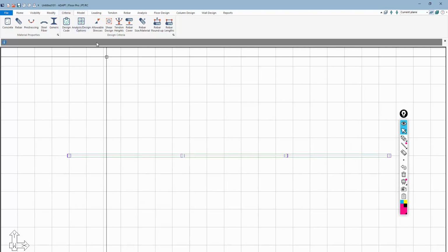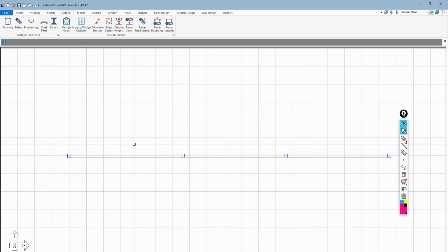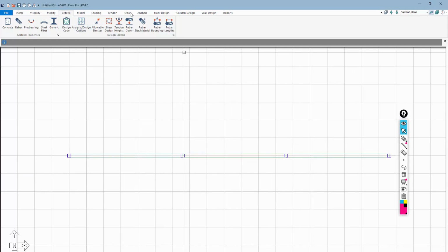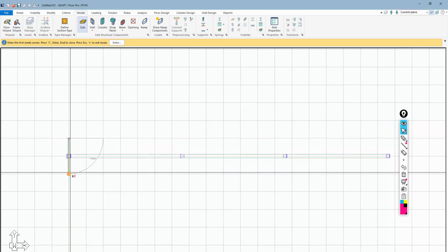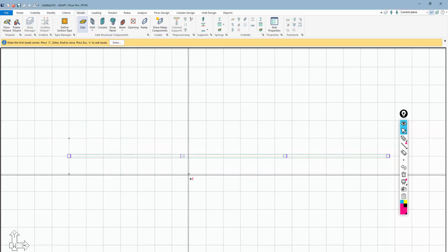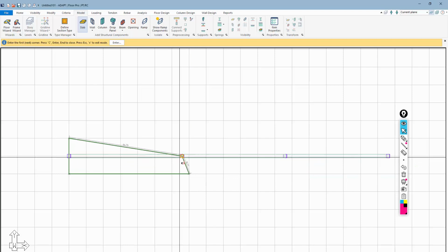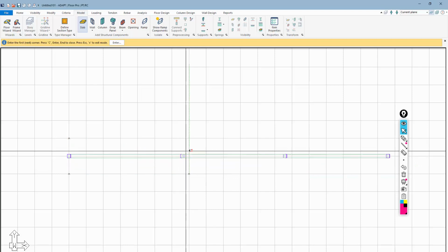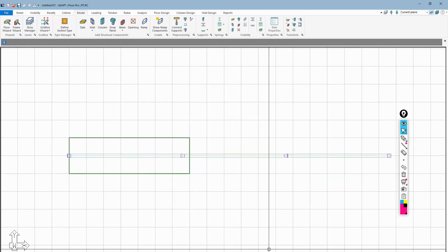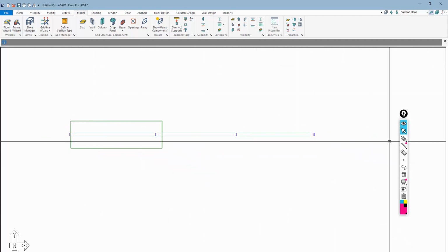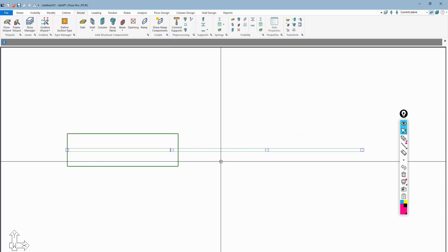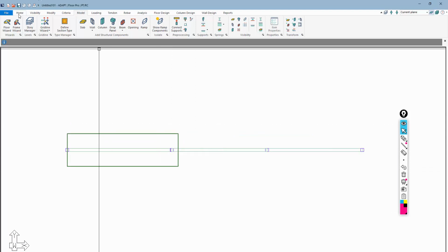Okay, so now because this is stepped, I actually need to create 3 unique slab regions. We'll go to Model, Slab, and we're going to just model this. Now notice here, this doesn't really correlate with the position of that column. So I'm going to abandon the use of that grid, and I'm actually going to use construction lines. We don't really have a background to build this, so I want to use some construction lines.